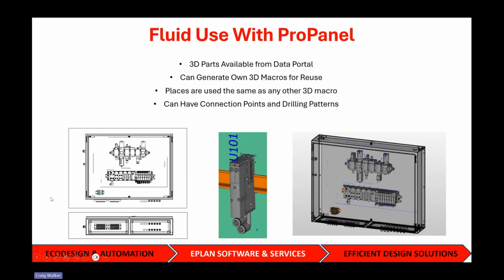You can generate model views of your ProPanel valve layouts. These are model views taken from the page space on the left. You can see the 3D macros come through with great amount of detail when they're brought in correctly. And you can see where you're aiming here, generating a beautiful 3D model of the entire panel. And this can be included or exported to the STP, included in the bottom of your PDFs, and it adds to the whole project presentation.